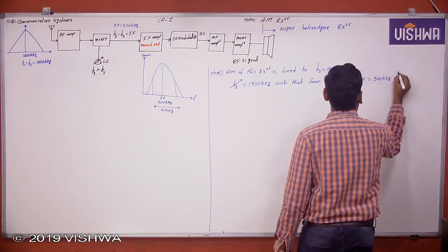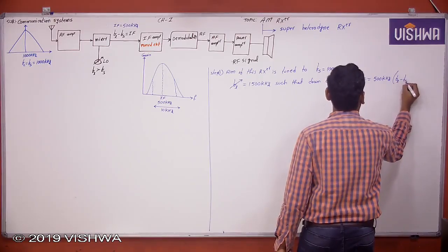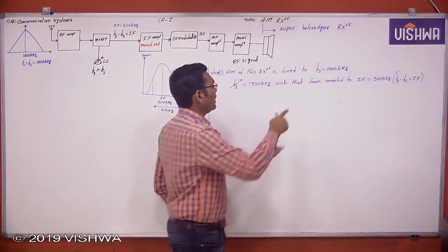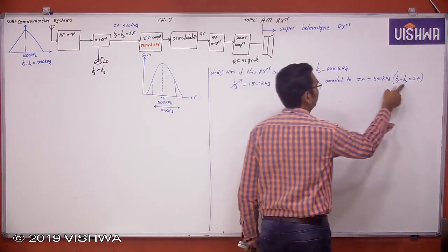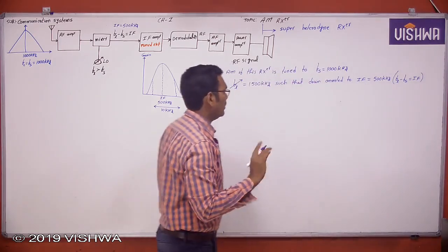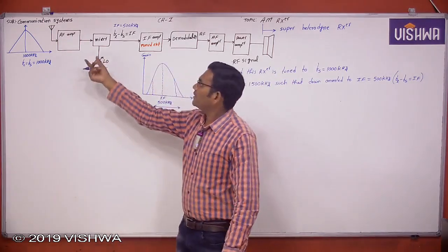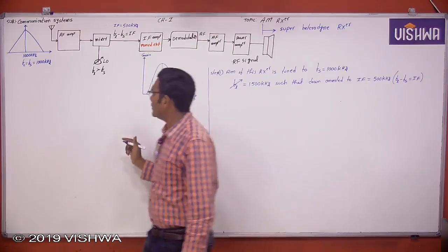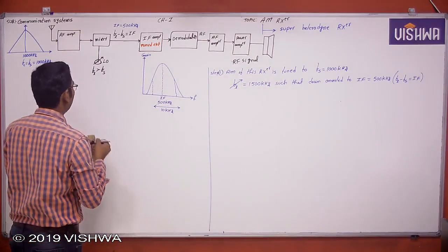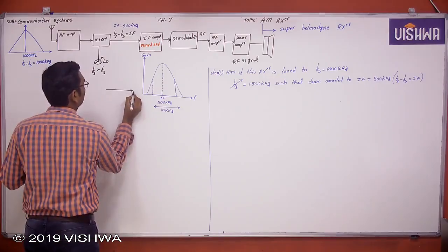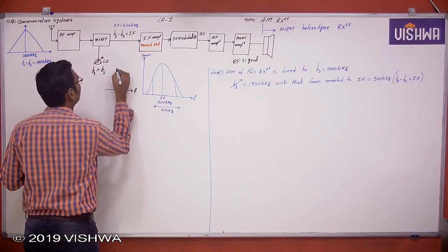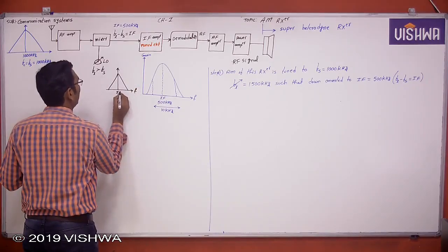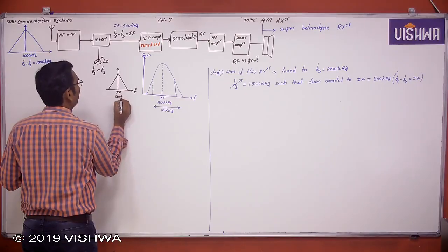Is it right or not? Because FL minus Fs is equal to IF. What is FL? 1500 minus Fs is 1000. 1500 minus 1000 is equal to 500 kilohertz. Okay. Now, the mixer down converts to a 500 kilohertz modulated signal. Now this is the signal which is down converted to IF, which is equal to 500 kilohertz.